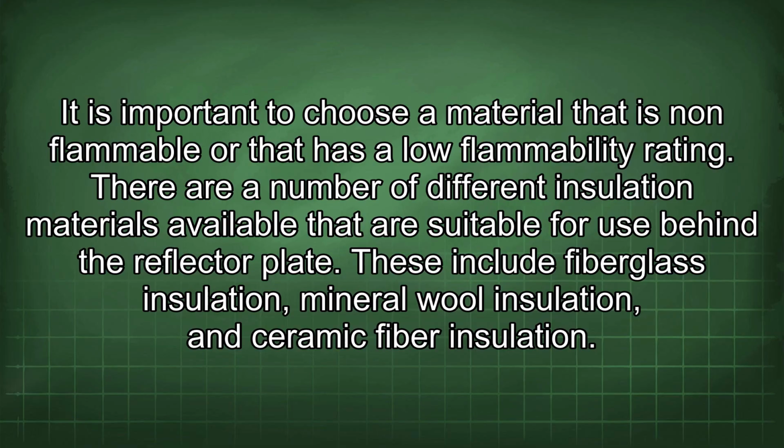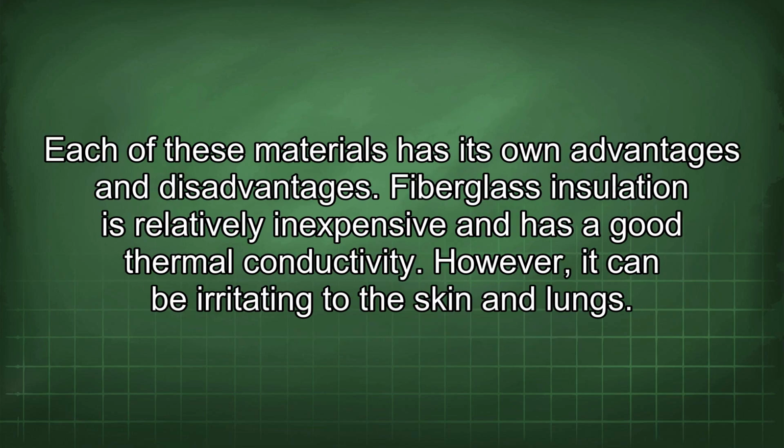There are a number of different insulation materials available that are suitable for use behind the reflector plate. These include fiberglass insulation, mineral wool insulation, and ceramic fiber insulation. Each of these materials has its own advantages and disadvantages. Fiberglass insulation is relatively inexpensive and has a good thermal conductivity. However, it can be irritating to the skin and lungs.